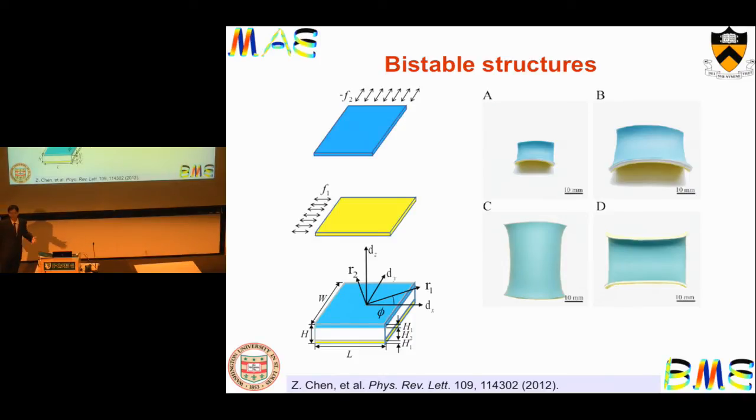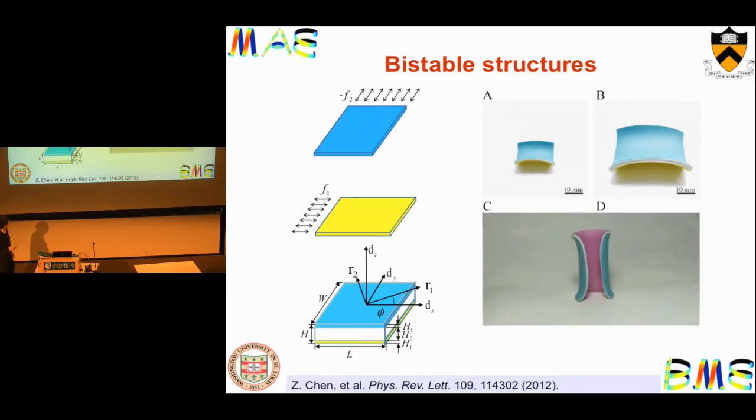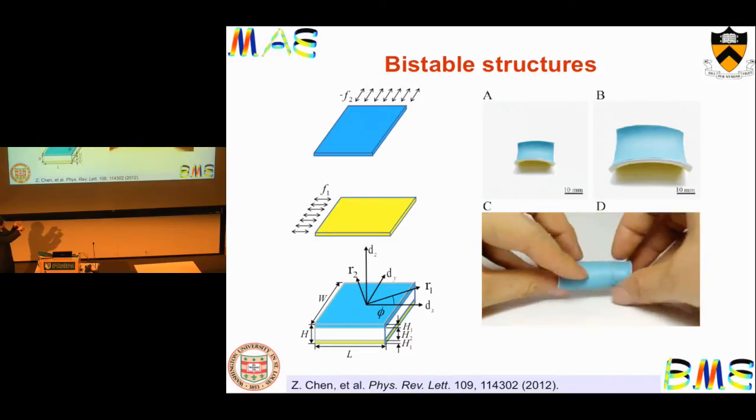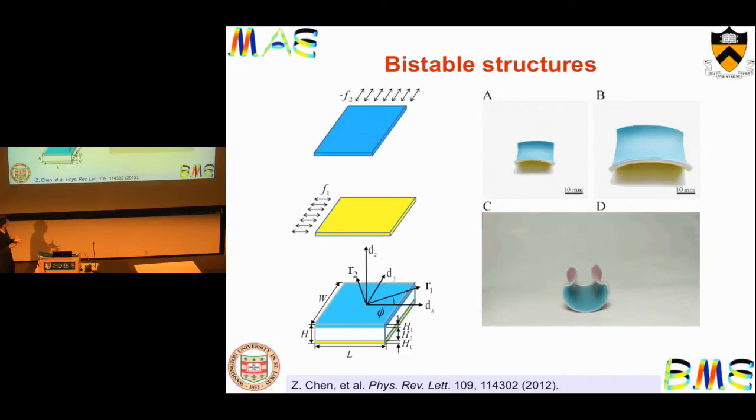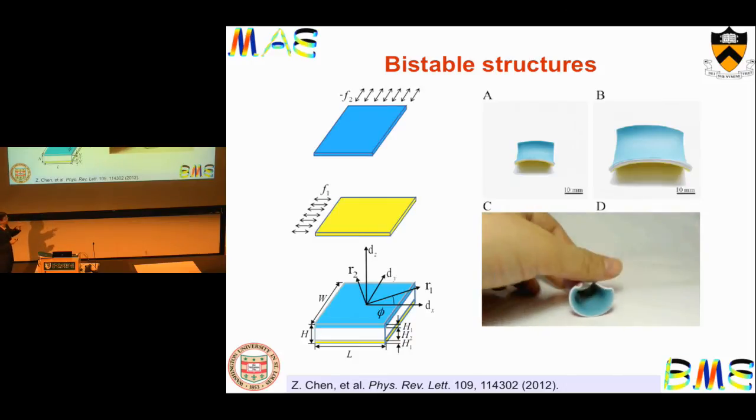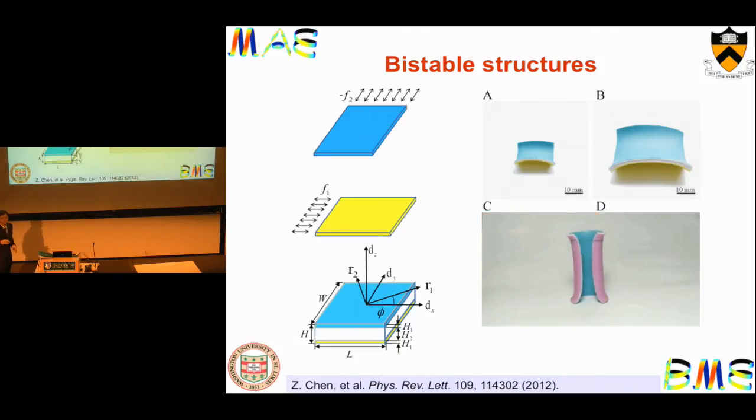And we can actually manufacture such a structure by a 3-layer experiment. So we pre-stretch the top and bottom layer with the same strain. And we sandwich a square sheet in between, so they're bonded together and let go. It's not surprising that the system will deform into a saddle shape because of the nature of the driving forces. Okay? But what is interesting is if we have exactly the same driving forces, but we just change the dimensions, we make the strip wide enough and thin enough, then interesting things start to happen. So the system now, instead of being stable in just one saddle shape, can be stable in 2 shapes. And you can apply a mechanical stimulus to make it transition from one shape to the other, pretty much like the slap bracelet.